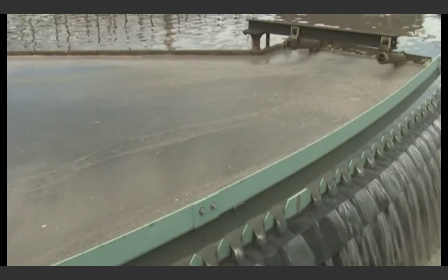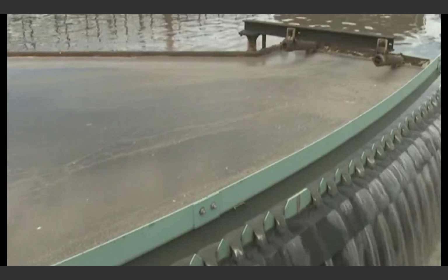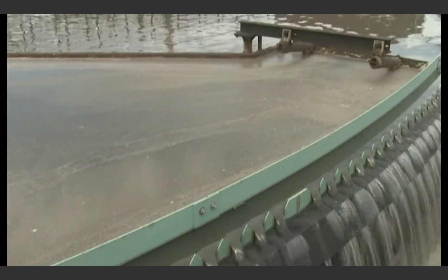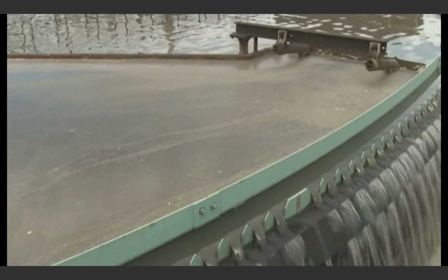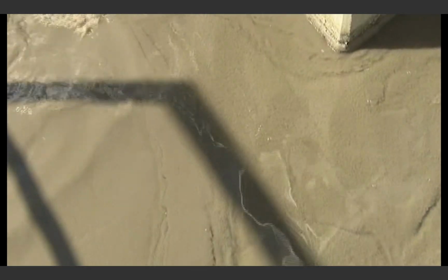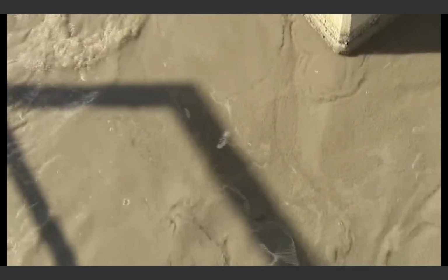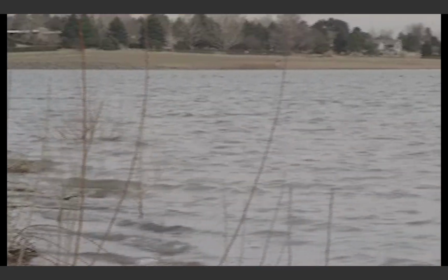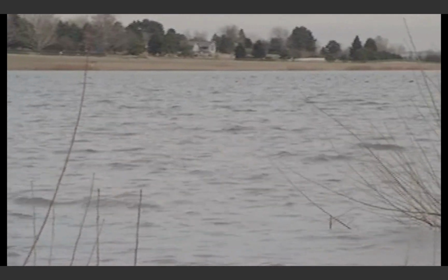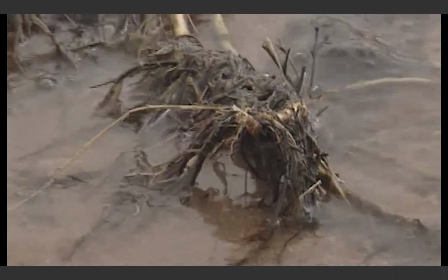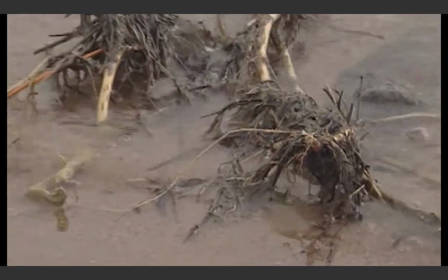As you can see, residential wastewater is in fact mostly water. It averages 99.9% water by weight, and a very small percentage, 0.1%, is waste. This small percentage is typically referred to as total solids. Total solids are a combination of dissolved organic and inorganic solids and solids suspended in the water.